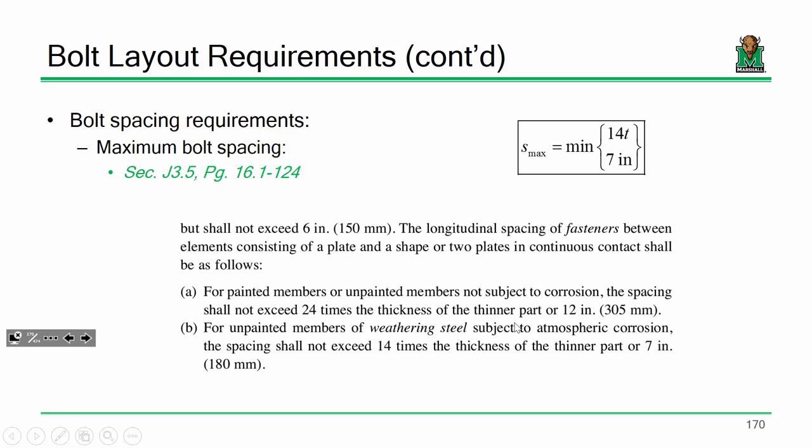So check-in bolt layout requirements is pretty simple. Calculate a minimum spacing, calculate a maximum spacing. Hopefully our spacing is somewhere in the middle. Sound good? A very common bolt spacing used in fabrication of steel structures is 3 inches. 3 inches, more often than not, will meet your requirements for most commonly available bolt diameters. We'll check that, but usually if you've got a grid of bolts and you keep a 3-inch spacing, you're going to be good on spacing requirements.